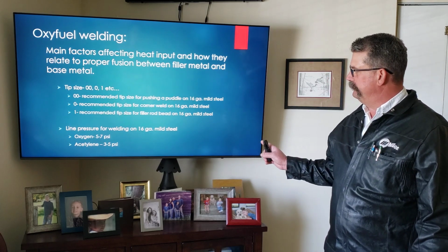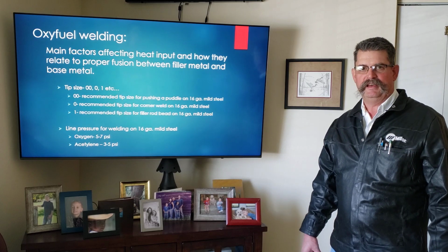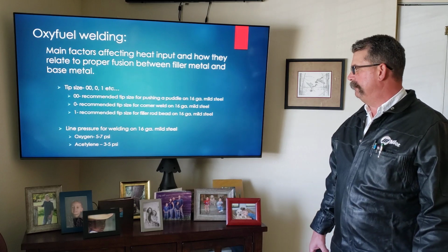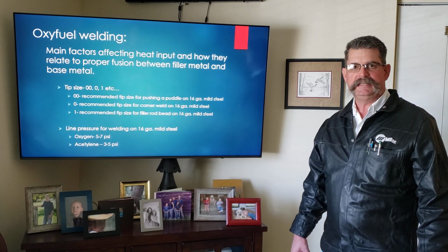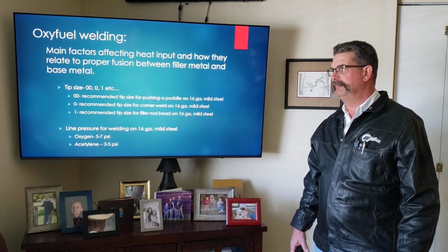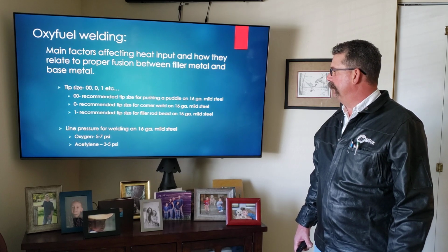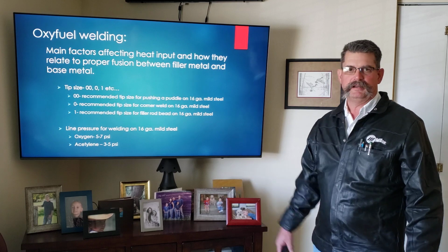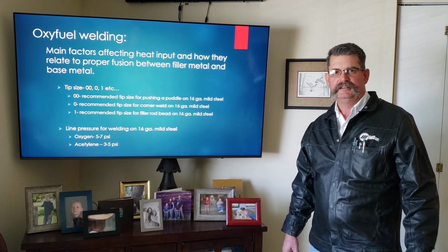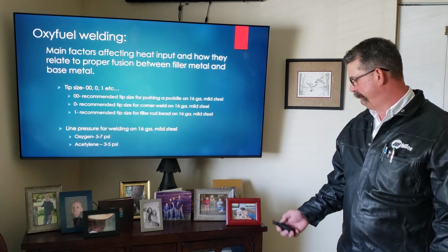We talk about setup in the oxy-fuel welding system, in that line pressure is very important for affecting heat and getting a good joint on welding mild steel with the oxy-fuel type welding practice. Line pressure recommendations there: oxygen 5 to 7 and acetylene about 3 to 5 psi.